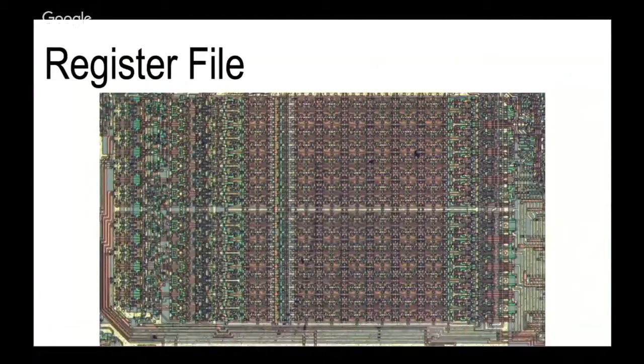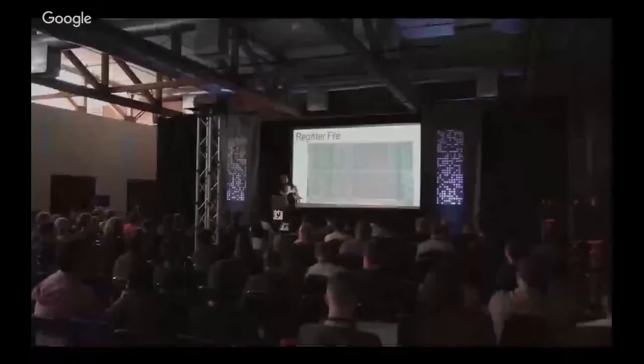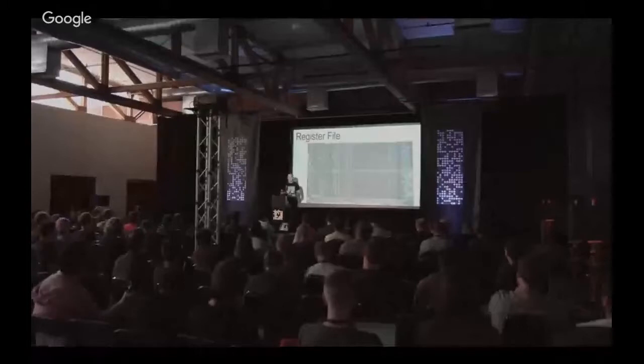Over here, we know the address lines are connected, so we can figure that this must be the program counter and the incrementing circuit for the program counter. And then the data bus is connected over here to read out the registers. If you go into a little more detail, there's some interesting things I found. There are secret registers, WZ. These are used internally for storage, even though they're invisible to the programmer.